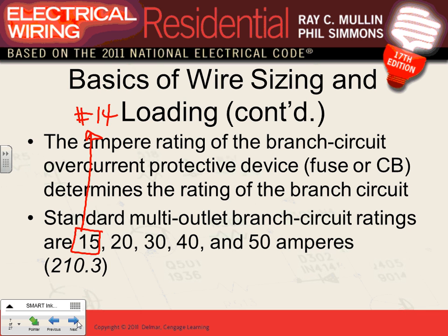Every time you have a 15 amp branch circuit, the smallest conductor you land on it is number 14, right? If you don't know that by now, the exceptions are motors. Later on we're going to talk about motors and exceptions. This branch circuit, typically for lighting in dwellings, we do it with 14. The second one is a 20 amp branch circuit.